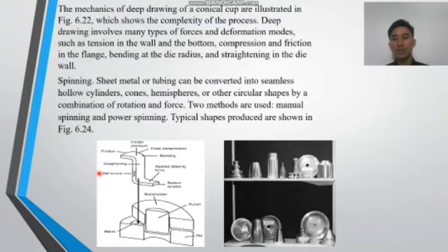Deep drawing involves many types of force and deformation modes such as tension in the wall and the bottom, compression and friction in the flange, bending at the die radius and strengthening in the die wall.